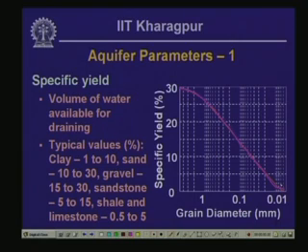You can see that for very coarse grained soils or rocks, you can have specific yield of up to 30%, whereas as the representative grain diameter goes down to approximately 0.01 millimeter, or actually 0.005 millimeter, you are going to virtually have zero yield from that type of soil.